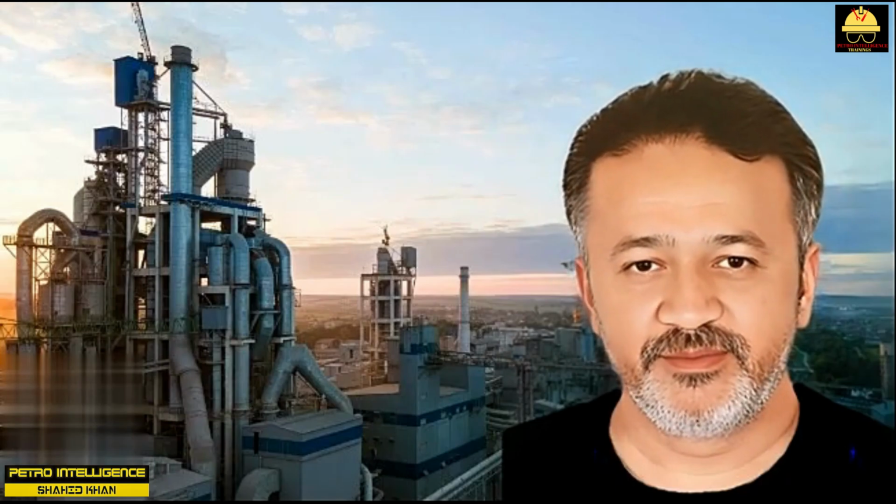Fin tubes. You may have seen bundles constructed with serrated, or very small, fins covering the exterior of the tubes. These are called low-fin tube bundles. These fins increase the outside surface area of the tubes by a factor of 2.5. However, this does not mean that the heat transfer efficiency of the exchanger will increase by 250%. Two factors curtail this improvement. One, let's assume that the controlling resistance to heat transfer is inside the tube. It does not matter whether this resistance is due to fouling, high viscosity, or low flow.